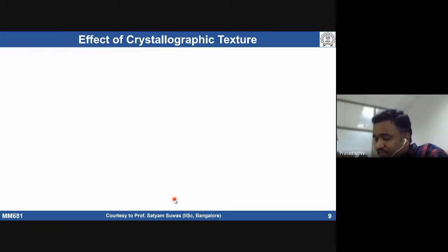Sir, impact strength, because there will be less stress raisers on the surface. Yeah, fracture toughness is also going to get affected, relatively. But some important ones are known very easily. We usually know tau C, the critical resolved shear stress, which depends on which orientation is favorable to the loading direction. Basically your yield strength is going to get affected, because if tau C changes, your yield strength of the material is going to change.